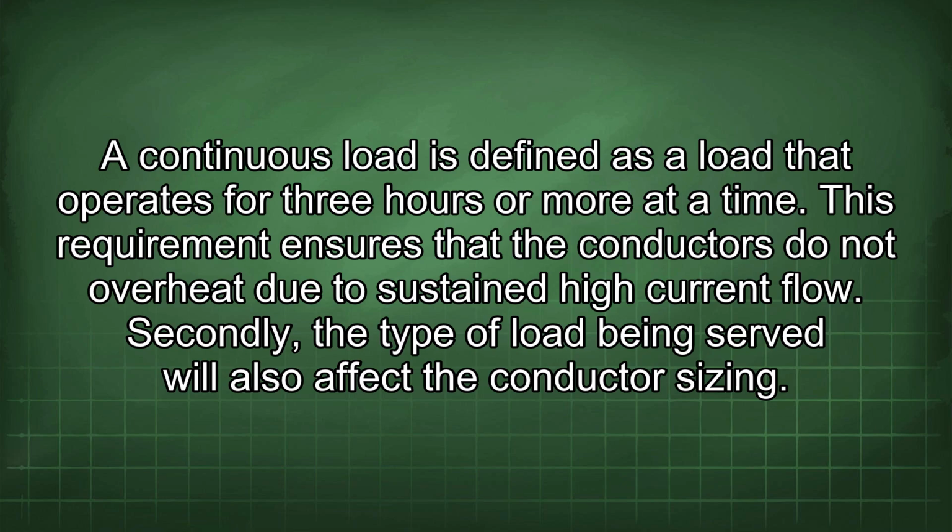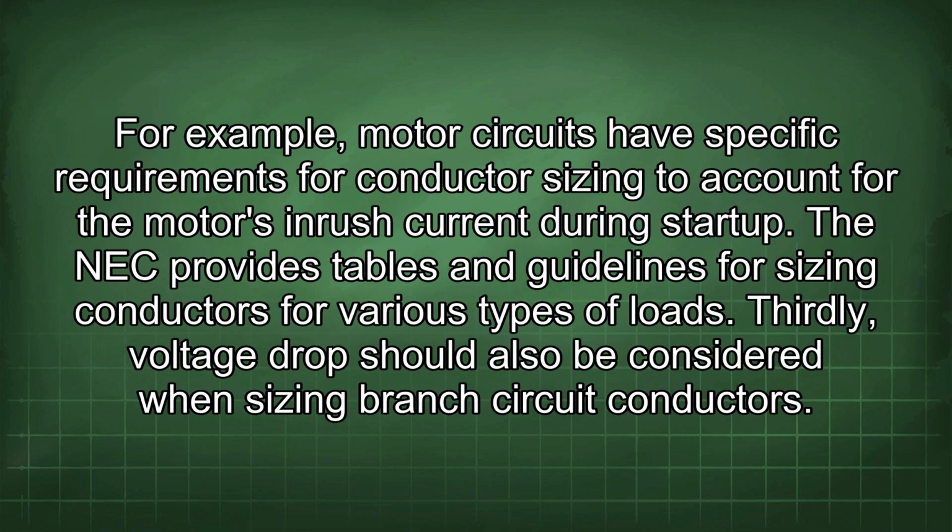Secondly, the type of load being served will also affect the conductor sizing. For example, motor circuits have specific requirements for conductor sizing to account for the motor's inrush current during startup. The NEC provides tables and guidelines for sizing conductors for various types of loads.